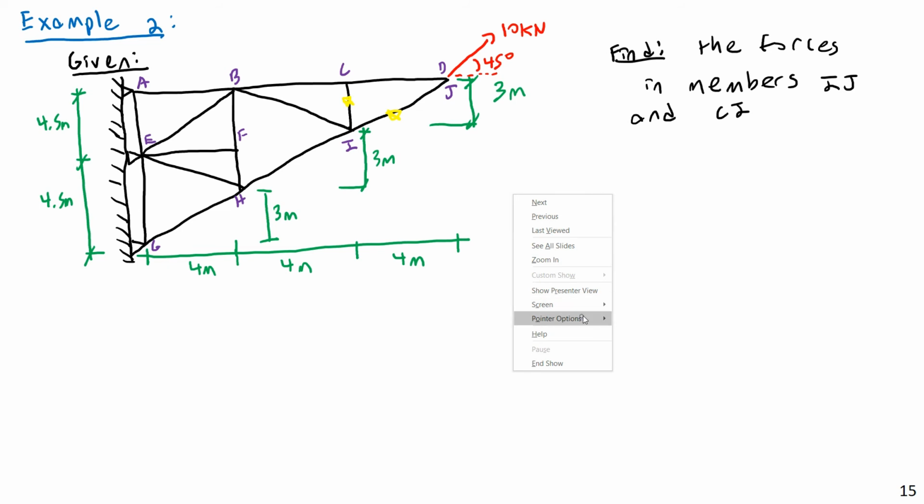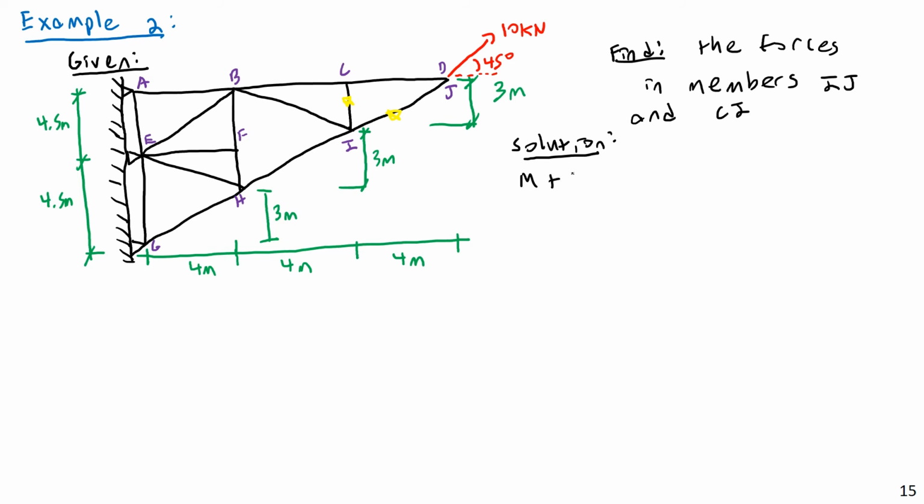Now, the next thing we want to look at is, well, I would like to determine whether this is, or prove whether this is or is not statically indeterminate. So, if we remember from last time, or from lecture 9, when we were discussing truss theory, one of the core concepts, one of the core equations, was m plus r equals 2j. And that is if a truss is to be statically determinate. So let's look at this.